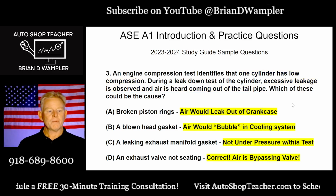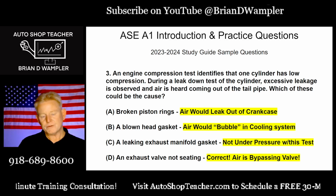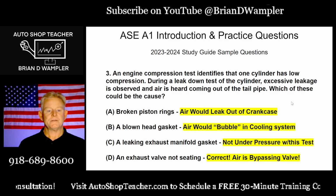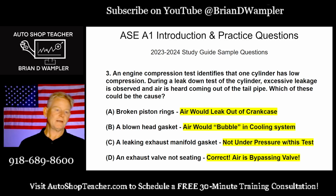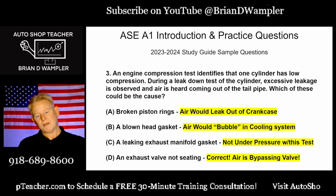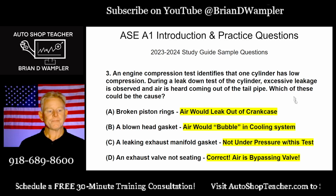If it was broken rings, air would leak out of the crankcase. So maybe taking off the oil fill cap or pulling the PCV valve or something where you could hear air coming past the rings, through the crankcase, and then out the ventilation system for the engine. If it was a head gasket, and it was leaking between the cylinder and the engine cooling system, like we saw in the last test question, well, we could take the cap off the expansion bottle or off the radiator, and good chance we'd see air bubbles coming out of there.